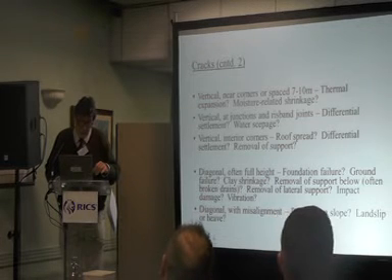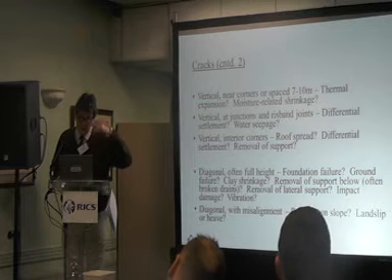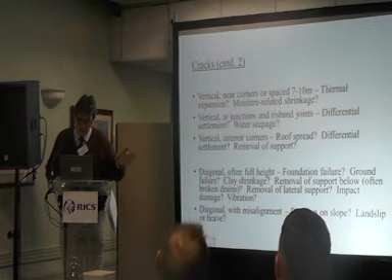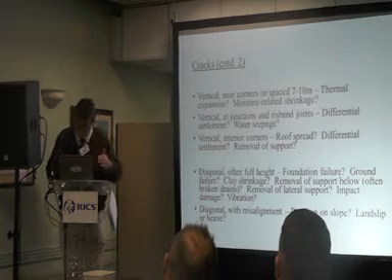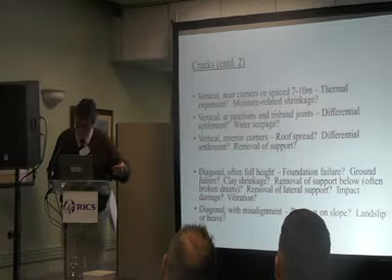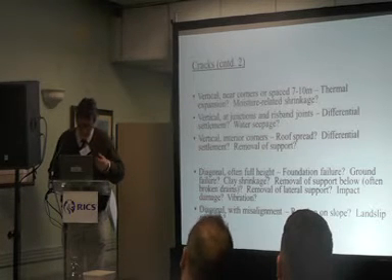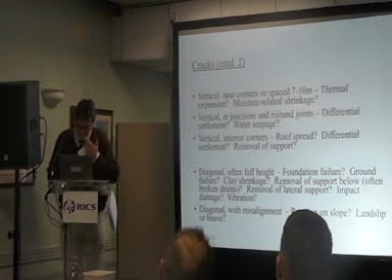Earlier this week I was in an old post office and looking at the accommodation above the post office. It's a listed building, and I was seeing at the internal wall little tears in the wallpaper, and sure enough, at some point they've removed walls to make the post office space on the ground floor bigger, and they've done nothing about supporting the partition walls. They don't need a lot of support, it's only a stud, but obviously it's inadequate because I'm seeing the cracks.